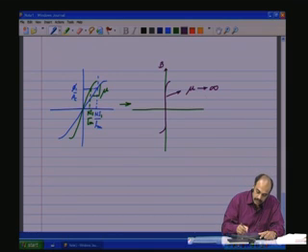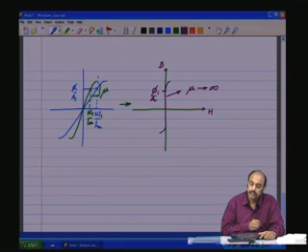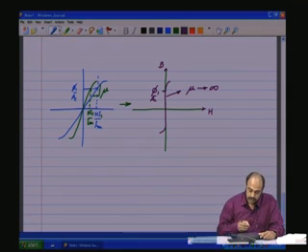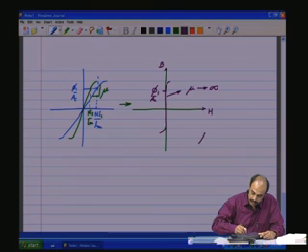This is the B and this is the H. So, what it implies, to obtain a flux phi m or phi 1, the current needed is negligibly small or infinitesimally small, or in the ideal case 0. So, that is another point of ideality, where mu tends to infinity.